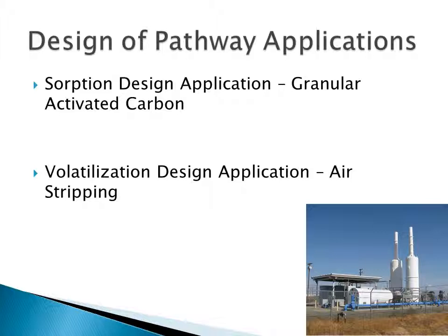Volatile contaminants can be effectively removed from groundwater, landfill leachate, and dilute aqueous recreational waste using air stripping. Air stripping is usually carried out in towers in which the water is pumped to the top of a system where it is distributed over slats, rings, or corrugated surfaces. Air is blown countercurrent to the water.